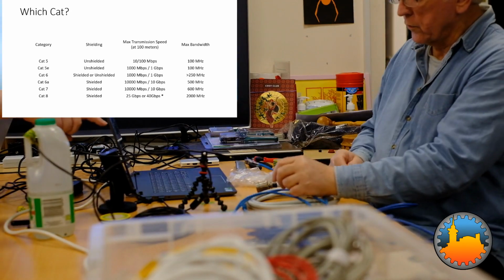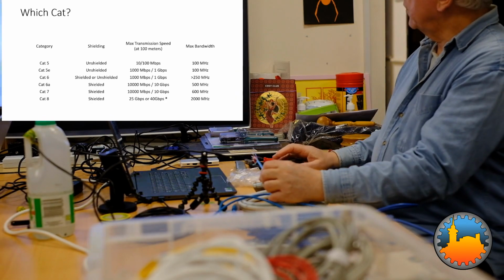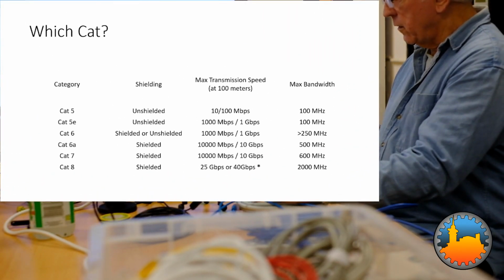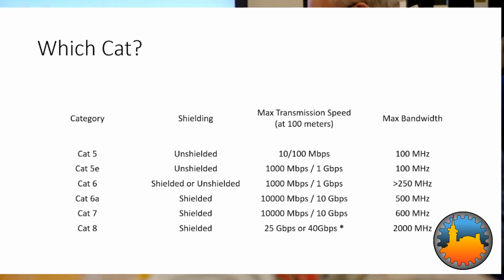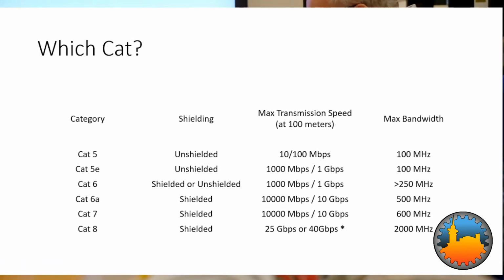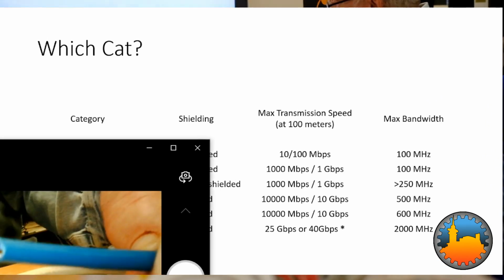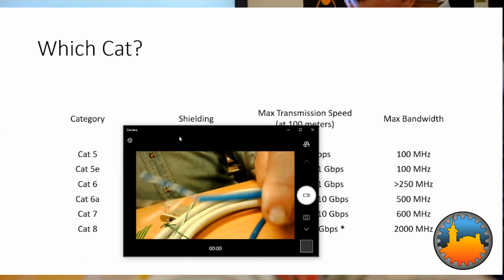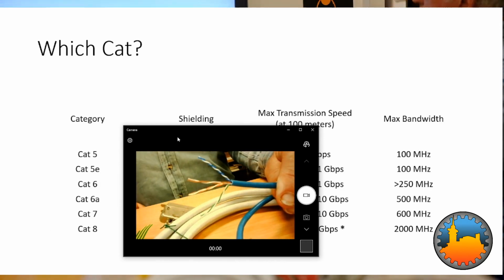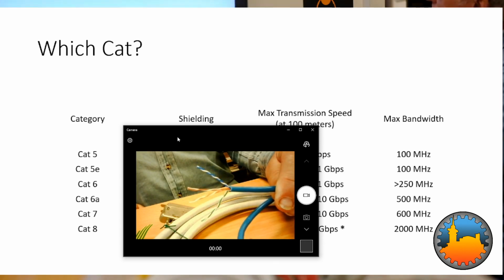The rate of the twist is what makes this thing work for each different sort of signal. So all those signals are kept separate, even though they're all right next to each other, by the fact that we're using twisted pairs, and the twisted pairs have got different twist rates on them.